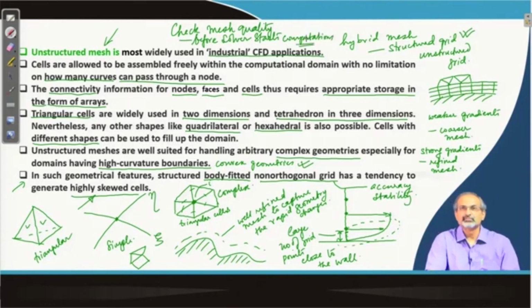So, if you are using some commercial or open source mesh generators, be careful that there should be such steps available where you can check the mesh quality, and if the quality is not acceptable, then there are some more iterative corrections which have to be done before the mesh actually comes up to an acceptable quality level before you offer it to the solver to do the computations.